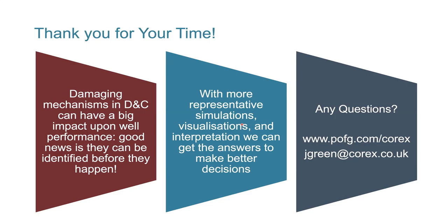We still have fluid loss to consider and where that cleans up from the pore network, especially with low perm carbonates. The lower perm the sample, the more pronounced the effect of losses of solids and fluid could be on the reservoir. With fractured carbonates, it's more of an issue of we need to think about what are the losses into fractures, does that clean up?